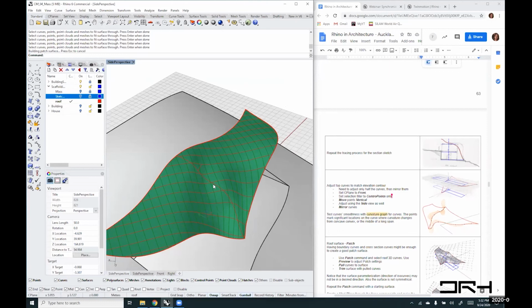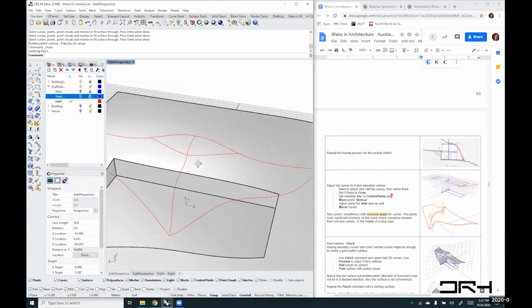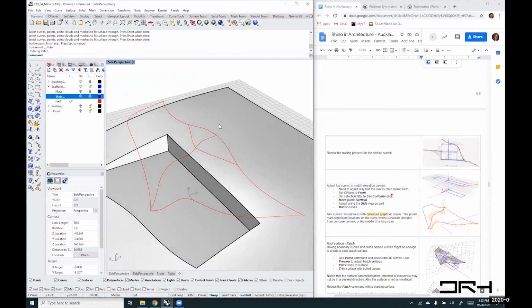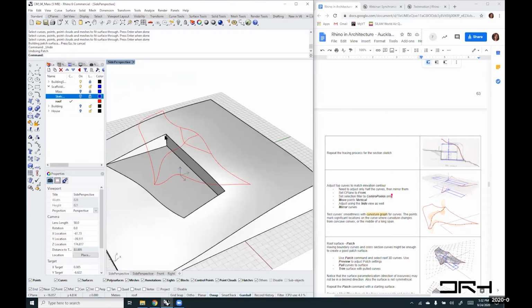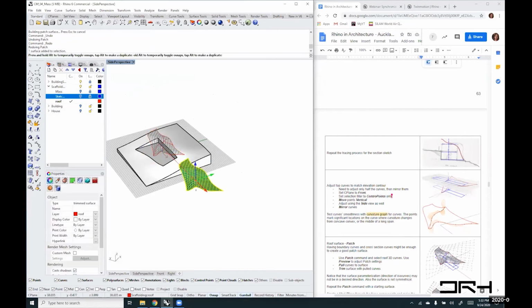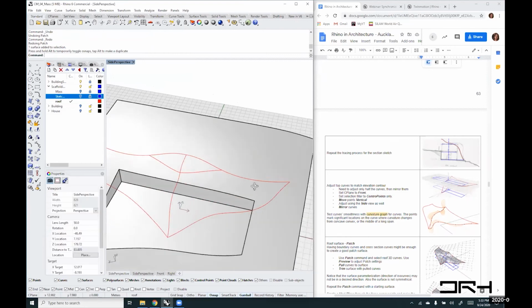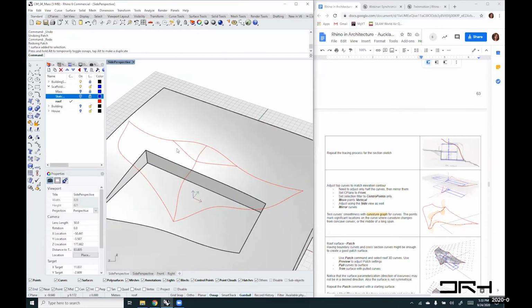And how can we create a patch that is symmetrical? So let's have another go. Let's try to use these other curves to see if it's helpful. But instead of replacing that, I want to keep that surface so we can also examine it later in terms of curvature. So that was our first patch attempt. Let's do another patch. This time we use the curves, but we use that other middle curve as well.